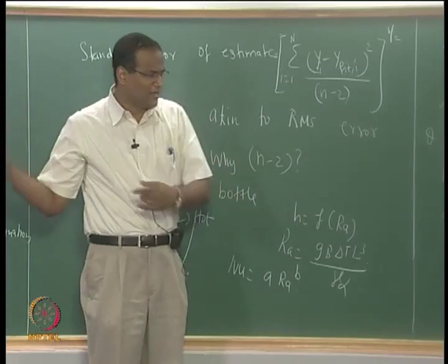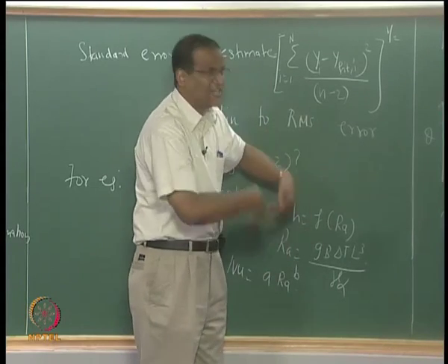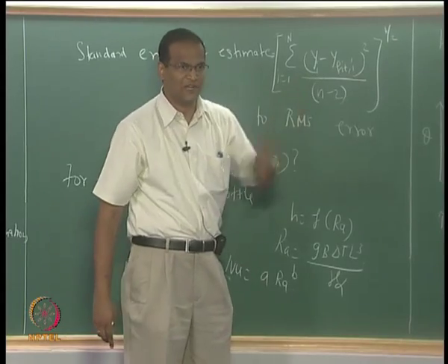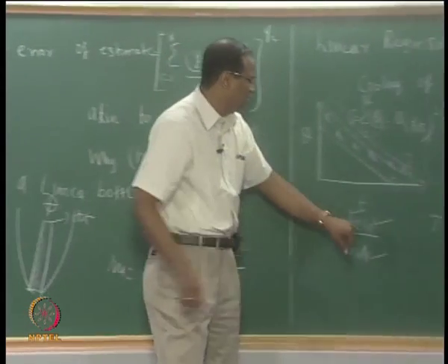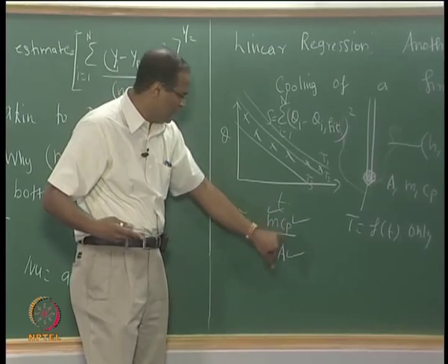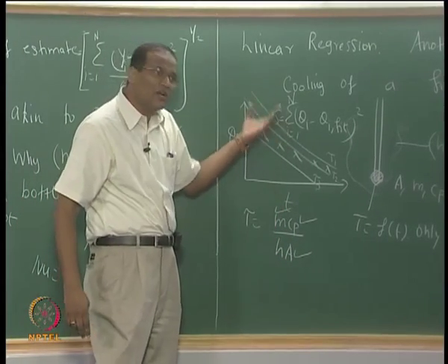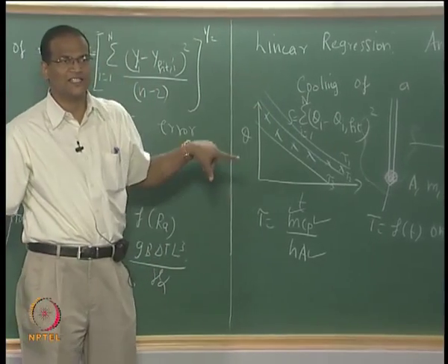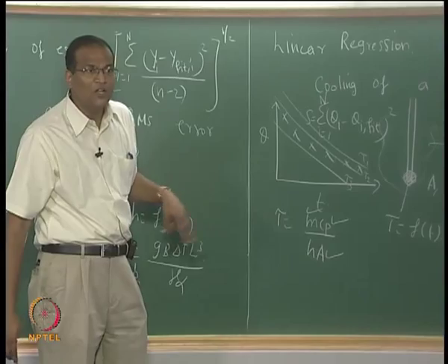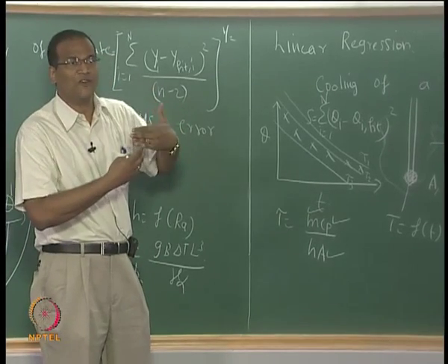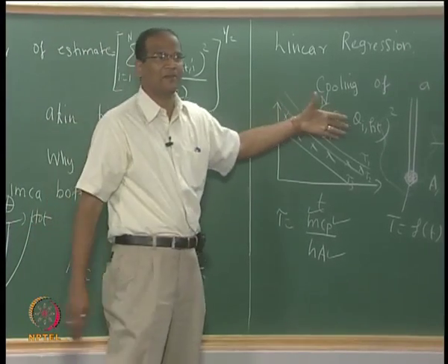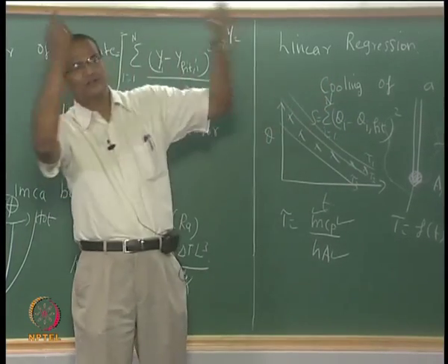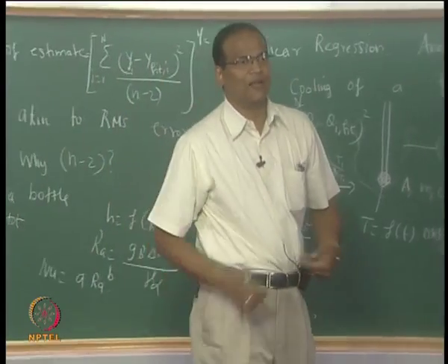But now what my students are doing is, if there is convection and radiation, how to simultaneously estimate the Nusselt number as well as emissivity. Or using unsteady data, can I simultaneously get Cp as well as h if I do not know what the material is. Or if this is not a lumped capacitance system, temperature is a function of x and t, can I simultaneously get alpha and emissivity, and so on. These are all inverse heat transfer problems, where you run some experiments, you know there is a mathematical model, and use least square minimization or regression to ferret out, invert or retrieve the parameters.